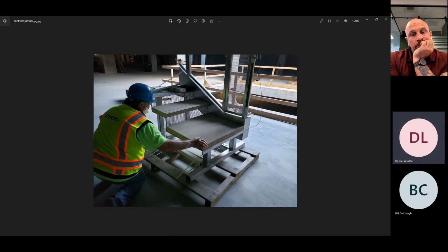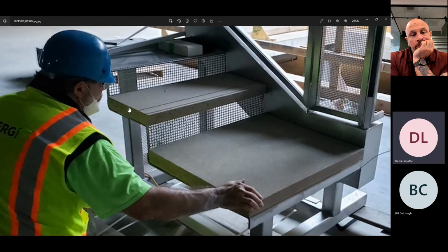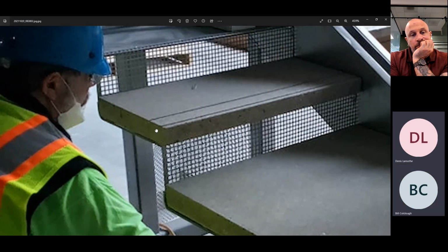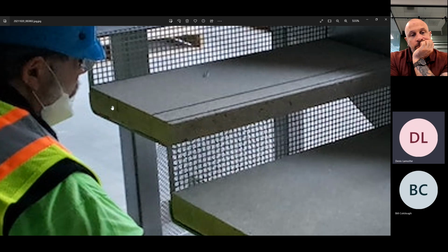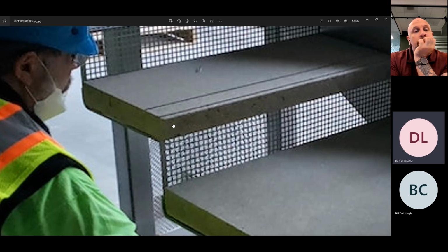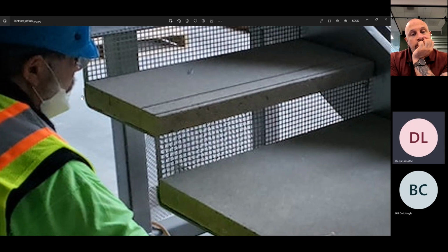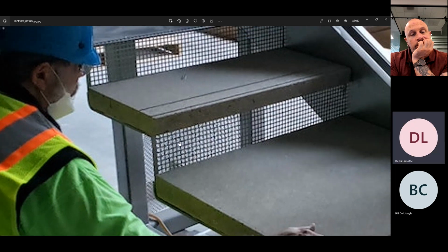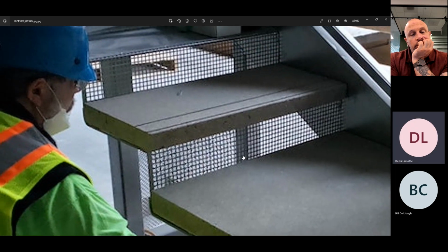I'll show you a mock-up. You might not see it too clearly here. This is for the Burbank project. Essentially, it was just a bent plate that gave you a flat surface for a precast tread with a slight rise in the back end just to give it some strength so that it wouldn't bow down with the weight. You might have this slight return in the back, or you might have it in the back and the front, depending on the visual look that the client wanted.